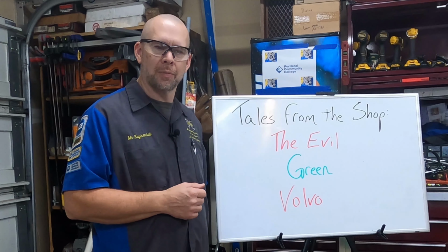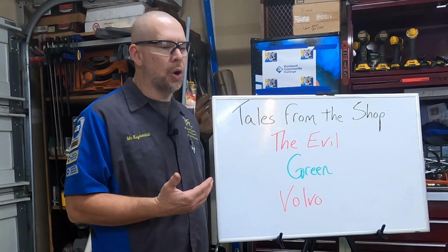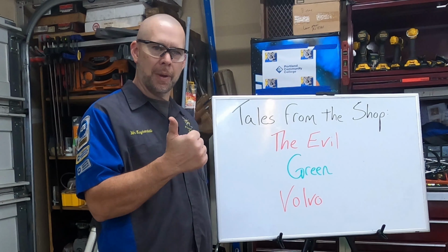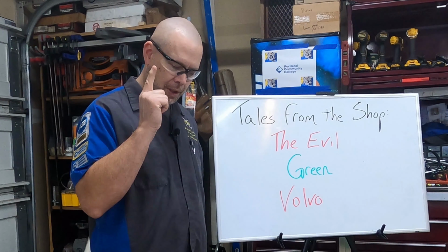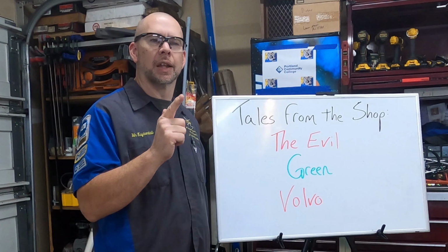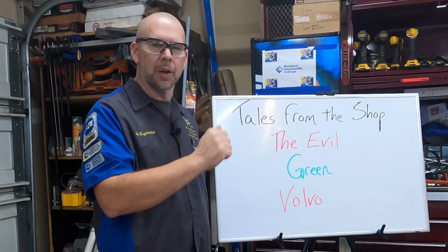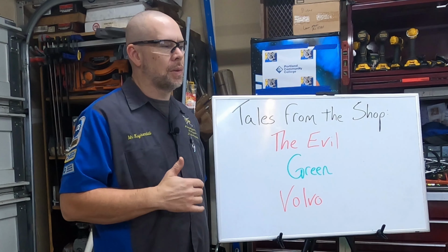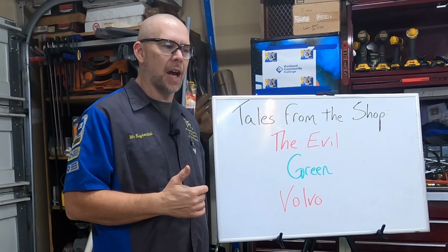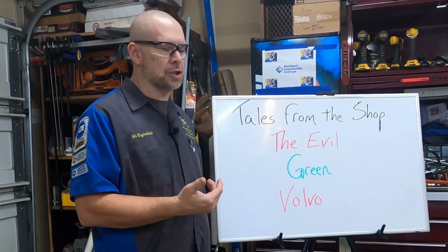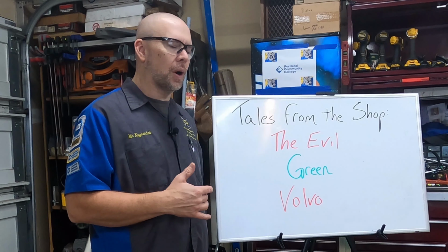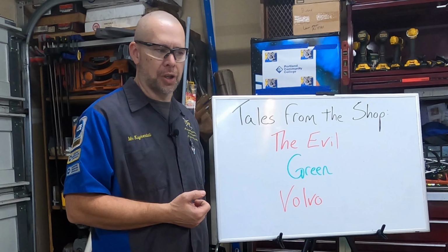Now I'm testing the high pressure pump. So now I know, because I have low RPM and I have high current draw, I have a restriction somewhere past that pump. That usually means I have either a restriction in the fuel filter or I have a fuel pressure regulator that's stuck shut.